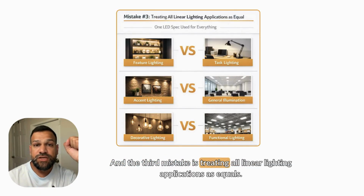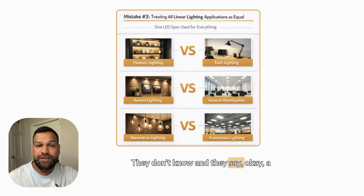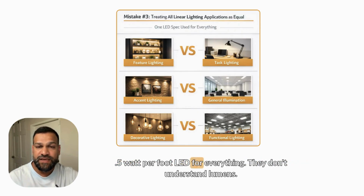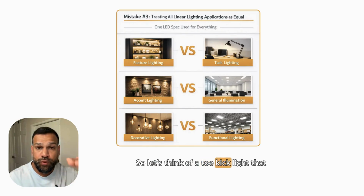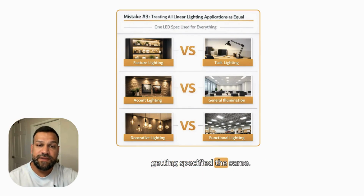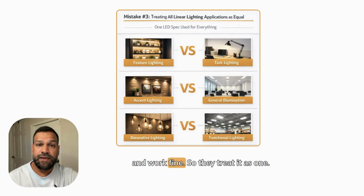And the third mistake is treating all linear lighting applications as equals. I commonly see this where the designer goes on Amazon, they don't know, and they say, okay, a 10 watt per meter LED for everything, or a 4.5 watt per foot LED for everything. They don't understand lumens, they don't understand what the application is. Let's think of a toe kick light that has this much space, and then a cabinet light, and everything's getting specified the same. And then they just dump a bunch of dimmers onto it and think it's all going to dim and work fine. So they treat it as one. So you have to know the application.